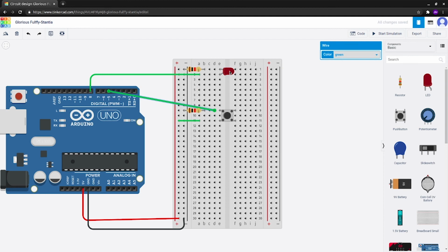Let's also connect an LED to the circuit so we can get an indicator of the status of the pin. To select two components, select one component, hold down Shift, select the other component, Ctrl+C and Ctrl+V, and you'll copy both components. Nifty, right? Okay, now let's hook this up. Okay, the alignment made it that I couldn't press this hole, so I had to press into here. But if you're doing this physically, obviously you can't put two wires into the same hole, so you're going to have to connect it here. Either that, or you could connect it here as well, under the resistor.